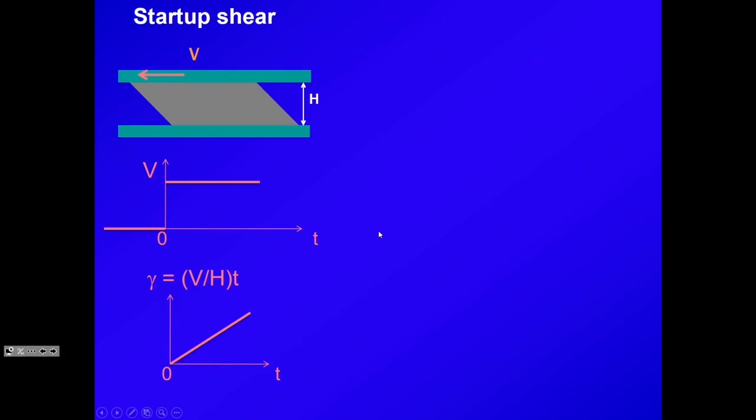This PDMS, for example, just to give you an example, I have to pretty fast try to smash this ball onto the table. It's a fraction of a second. So in that limit, it's elastic, okay? It's fairly elastic. However, the tau of this polymer is only a second or so, okay? Pretty fast, okay? Fast in what sense?